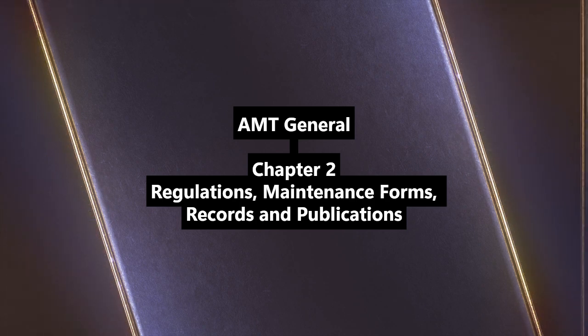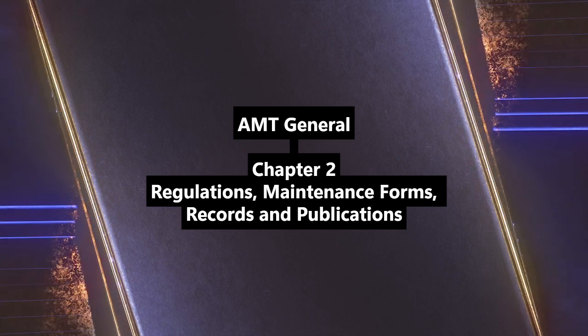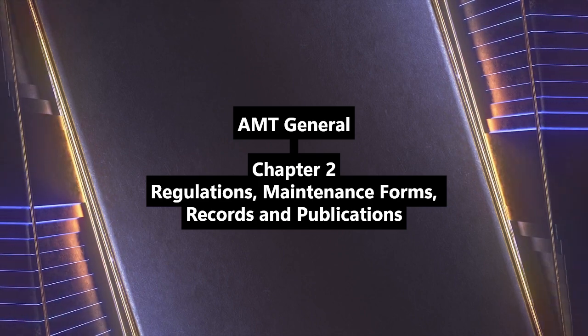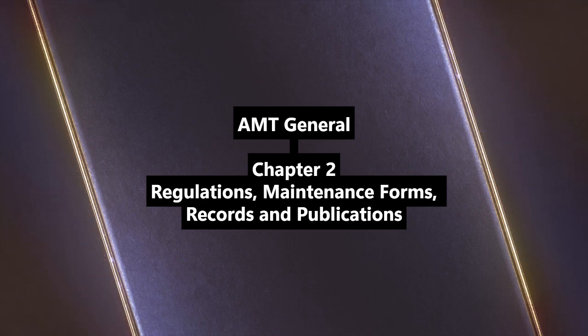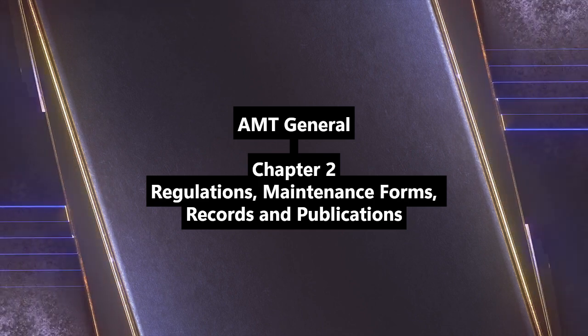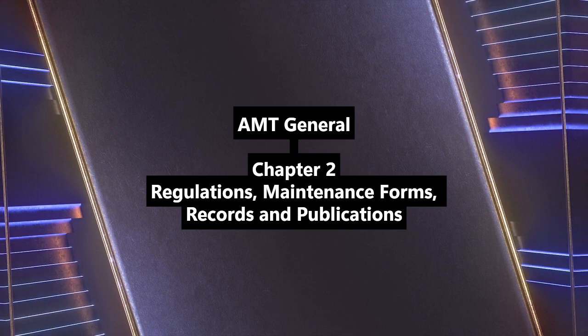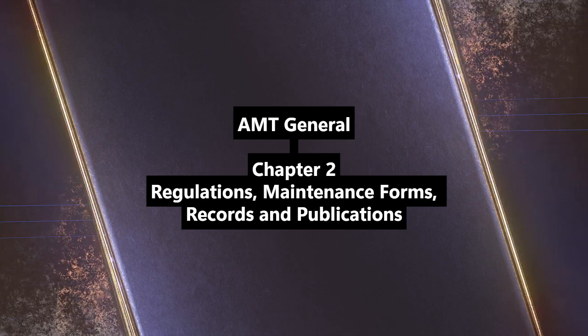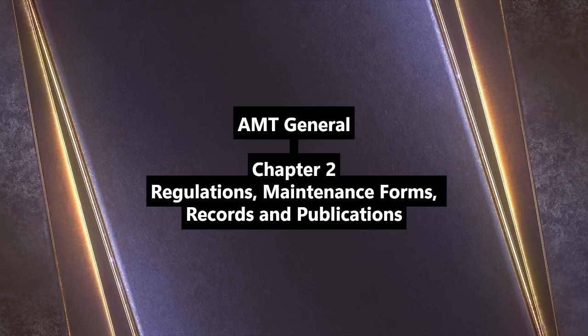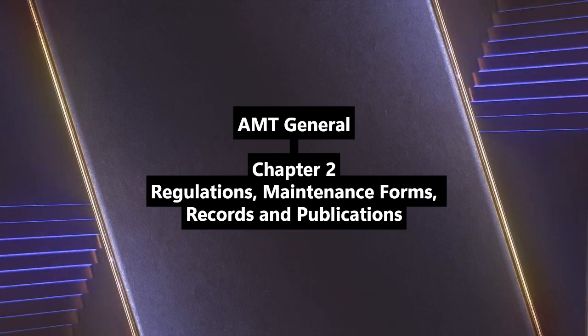We have temporary records, 91.417(a)(2), kept 1 year or until repeated or superseded. Maintenance, alterations, inspections. Need description, date, signature, cert info. And permanent records, 91.417(a)(1), kept by owner, transfer with aircraft. Total times, life limited status, time since overhaul, inspection status, AD status, Form 337s for major alterations.